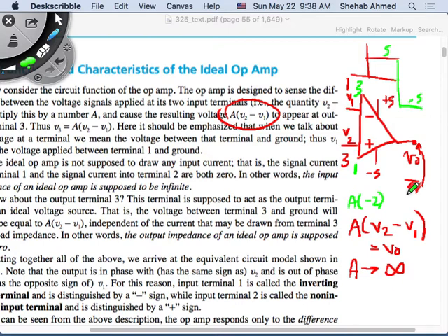I want to have a signal at the input and amplify it, multiplied by 2, multiplied by 2.5, or multiplied by 3, right? You want to be able to take this signal and put it into an ADC afterwards. Analog to digital converters, their input will be 0 to 3 volts, for example. You cannot just saturate it to the supply rail and that's it. So what do you do? You build circuits around it.